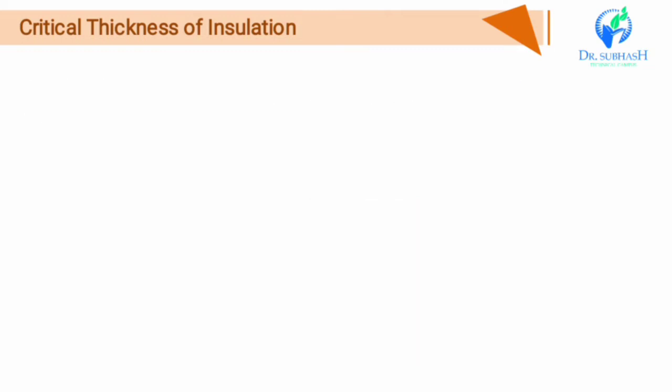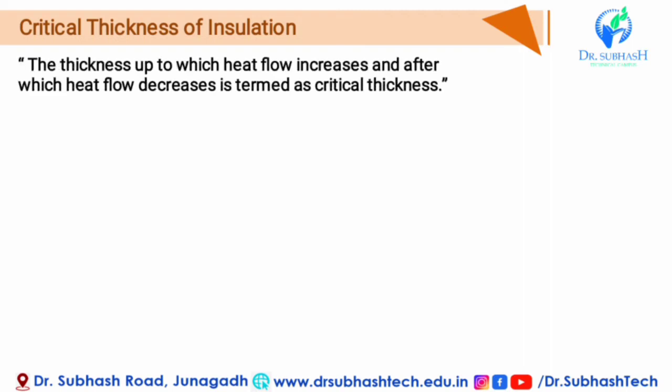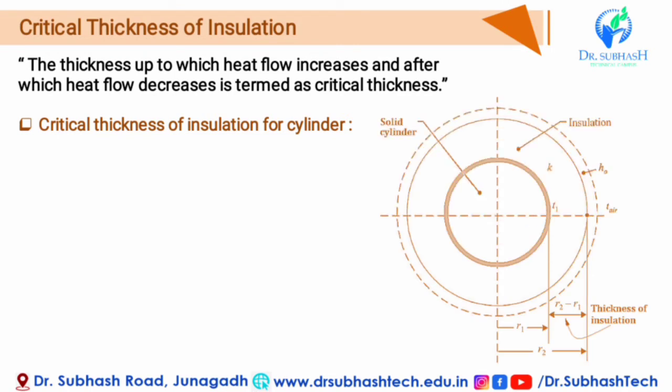As I said, under certain circumstances, insulation actually increases the heat flow up to a certain thickness. The thickness up to which the heat flow increases and after which heat flow decreases is termed the critical thickness. Let's derive the formula for critical thickness of insulation for a cylinder.